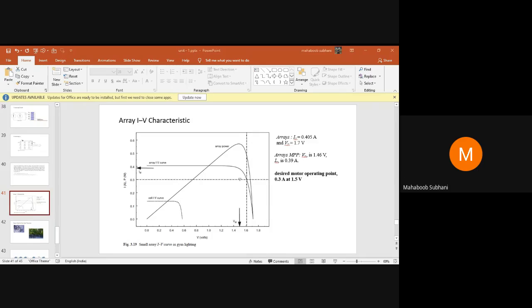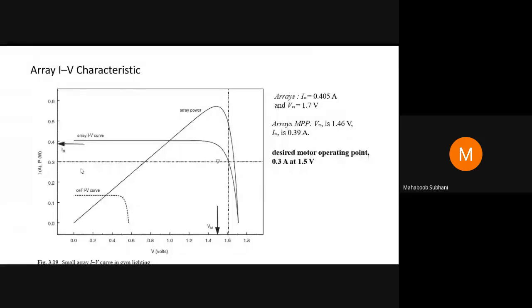Now what we have to do is put some equivalent resistance, which is equivalent to 0.33 ohms. So if you place any resistor which has 0.33 ohms value, then we will be able to get the desired speed of 1.0 meter per second. Okay. Now, if I want to have this extra resistance, there may be changes in this solar panel cell design.